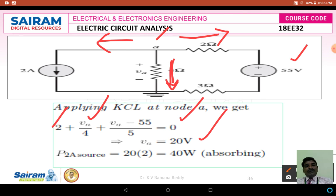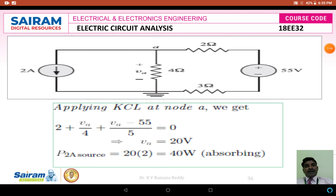Now VA equal to 20 volts is the voltage across the current source, because the current source is connected across these 4 ohms. So across these 4 ohms is the voltage VA, which is 20 volts. If I want to calculate the power across the 2 amperes current source, what is the power formula? P = V times I, because we already know the current I is 2 amperes. The voltage is 20, therefore 2 times 20 is 40 watts. 40 watts is the amount of power absorbed by this 2 amperes current source.